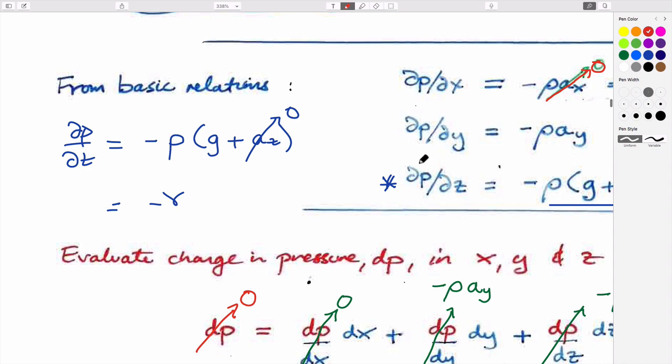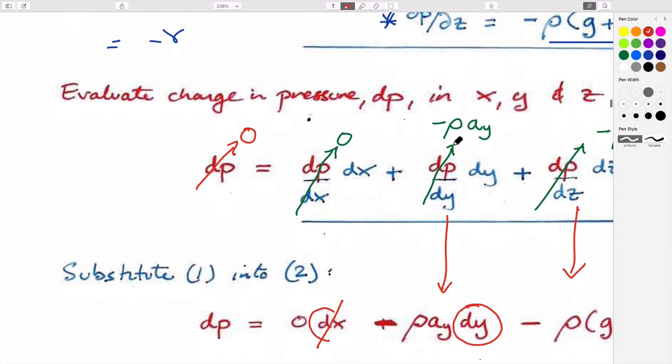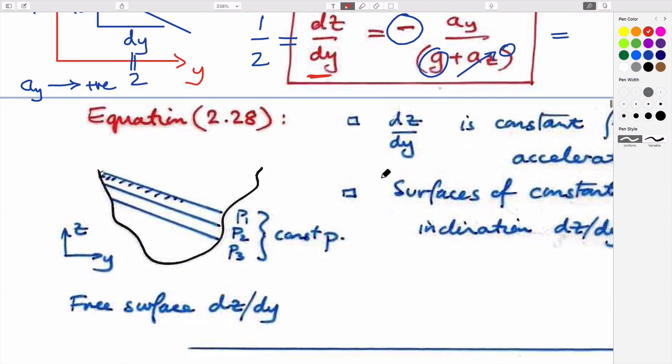You know from this that as you go horizontally, the pressures will change according to the acceleration in the y direction. You can see that here if you drew a line across here: the fluid pressure as you went down from this free surface to this point is higher than here. And so you'd expect that as you go from this point to a horizontal point here, the fluid pressure would change as you go laterally.